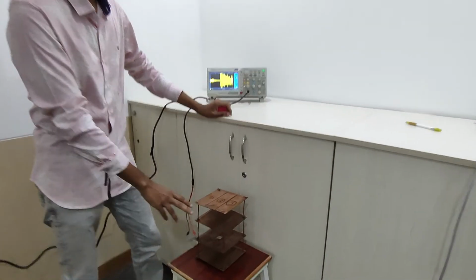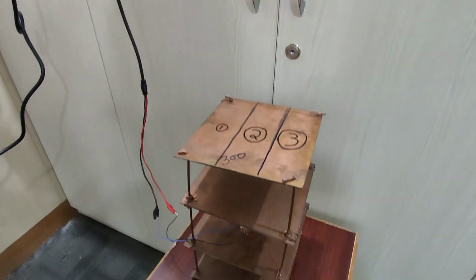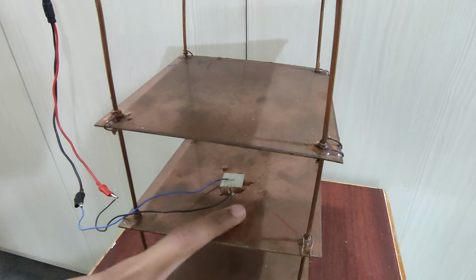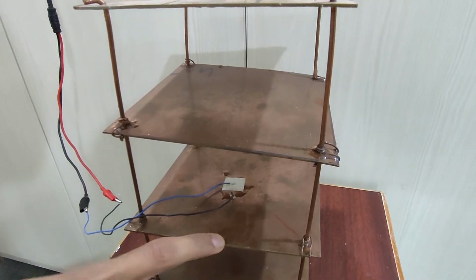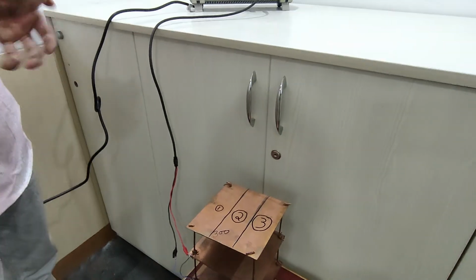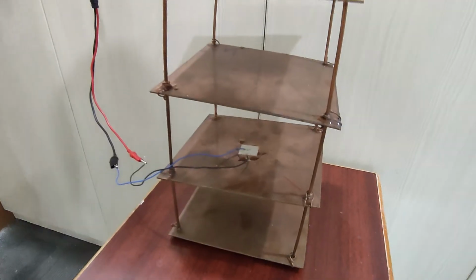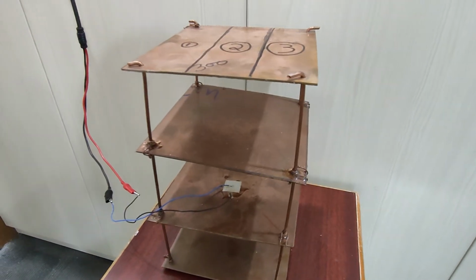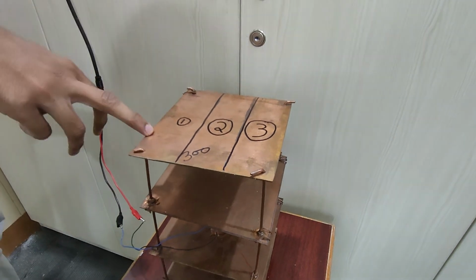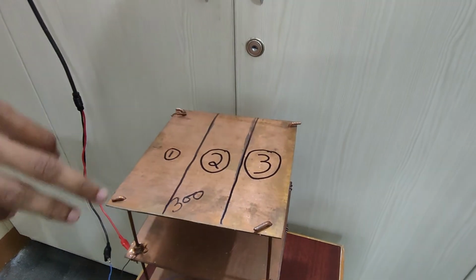We have prepared a 3 days plan. Then we bonded the sensor to the first floor over here, and we used epoxy as the bonding agent, and we soldered these wires to the positive and negative terminals. Once the soldering is done, we put an epoxy layer on top of it to prevent any further ruptures. Now we are going to collect 3 excitation points from the first floor: 1, 2 and 3, as we divided over here.